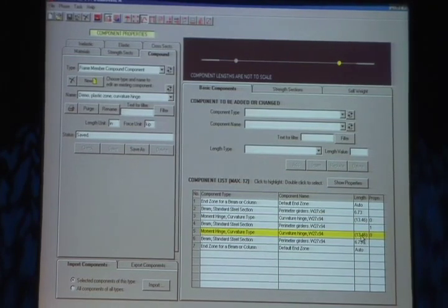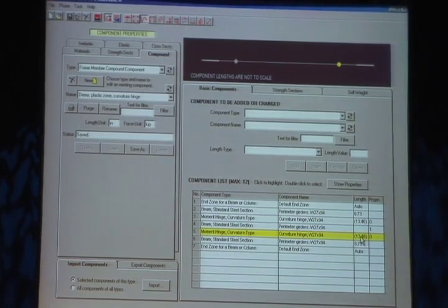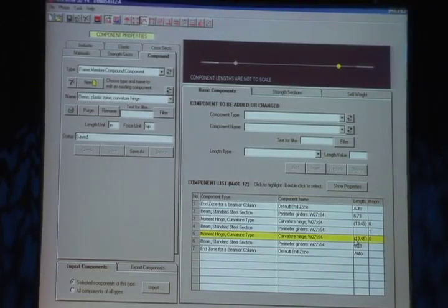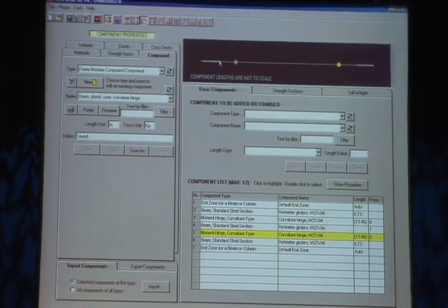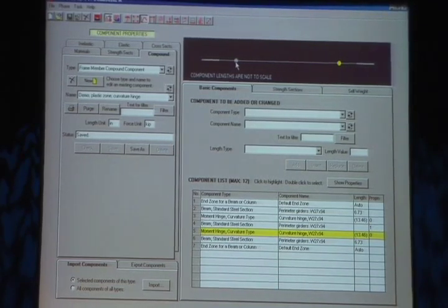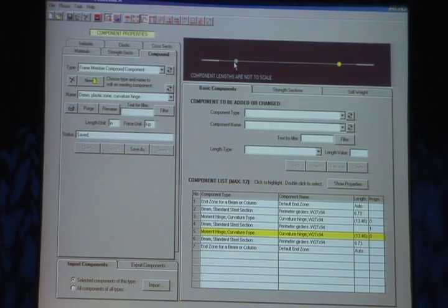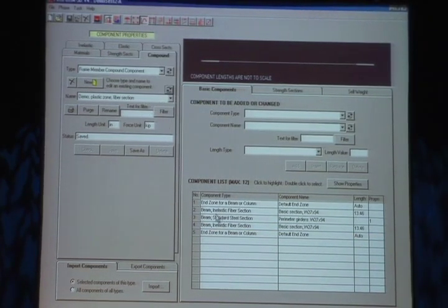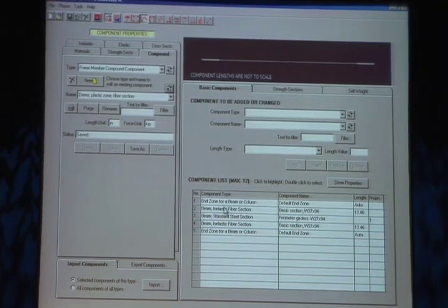And it would take me a little while to explain this. But basically it says that this 13.46 is 1/2 the depth of the beam. So it's actually saying, let's use a plastic zone here with a moment curvature relationship designed by this hinge. And let's make this plastic zone 1/2 the depth of the beam. So you position it 1/4 the depth out, you assign a tributary length 1/2 the depth, and you've got a plastic zone model.